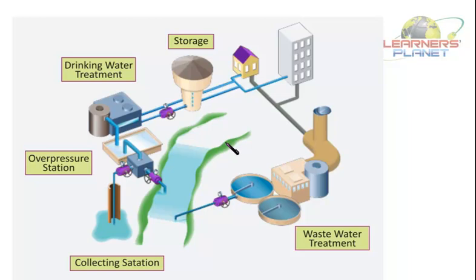First of all, there are suspended solids, also called physical particles, that can clog the rivers or channels as they settle down under gravity. Then comes the biodegradable organics, which can serve as food for microorganisms in the receiving water body, right? Microorganisms combine this matter with oxygen to form water and to yield the energy they need to thrive and multiply.